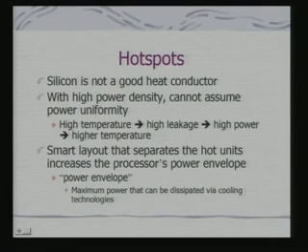So, one issue in terms of real VLSI design is that you would like to look for a layout that separates the hot units, typically the hot spots, and that can increase what is called the processor's power envelope. What is the power envelope? The maximum power that can be dissipated via cooling technologies. So, if that is more distributed, the power envelope can increase.